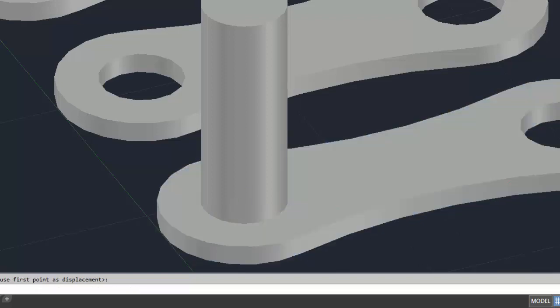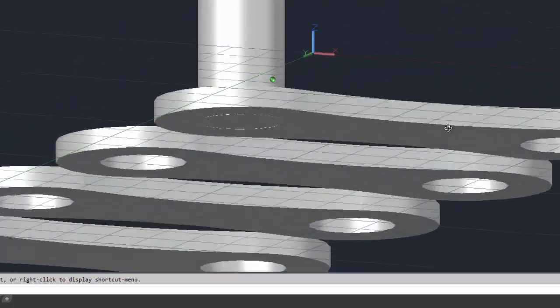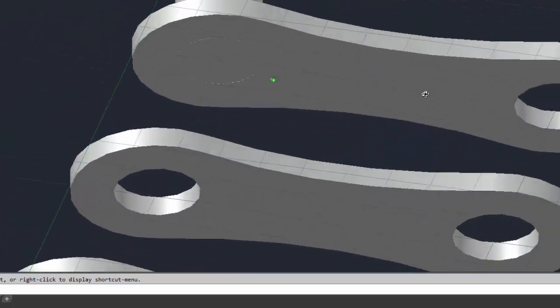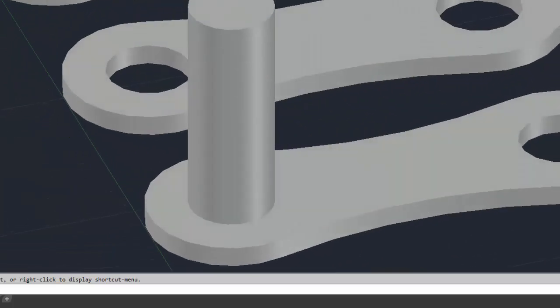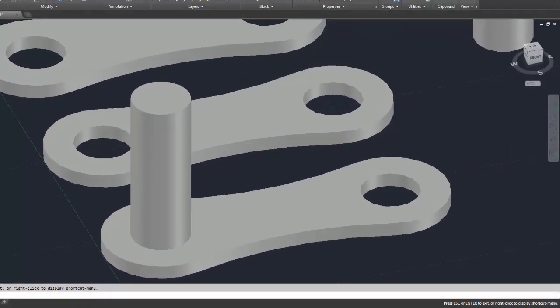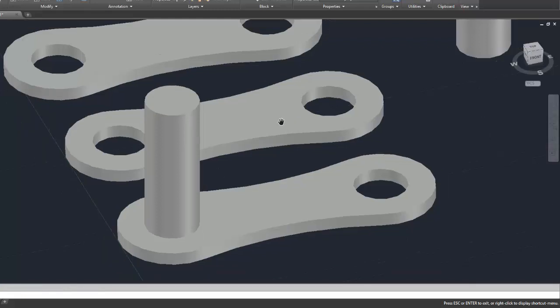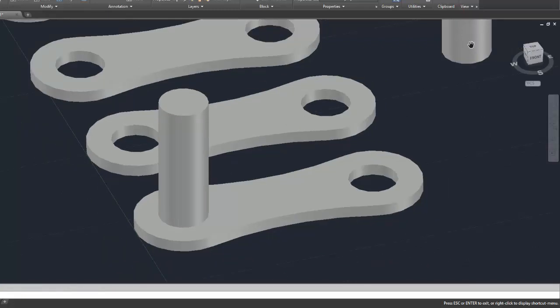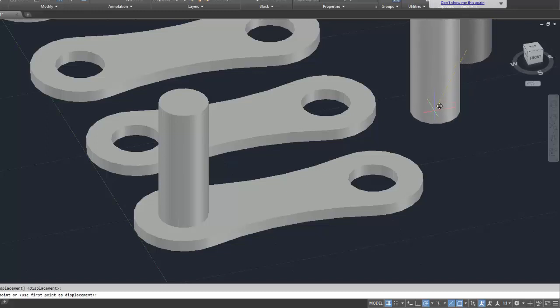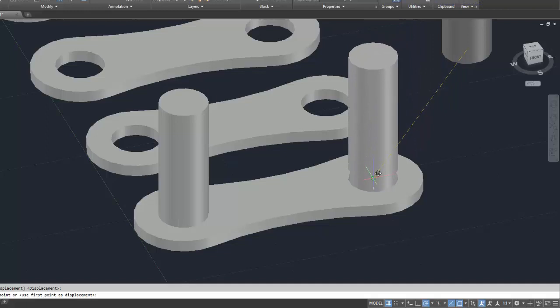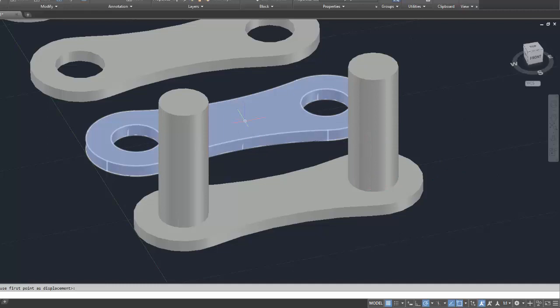Okay, and just to prove that it's all the way through, you can do an orbit. You can see now that the bottom line of the bottom surface of the pin is dead flush with the bottom of the plate. Now just to move that over a fraction, in fact I'll need to zoom out just a little tiny bit. I can see the bottom of this one now, so I'm going to move that pin, right click by the center point, back over. You see the 2 center points, top and bottom. We click the bottom one, and that one's done.